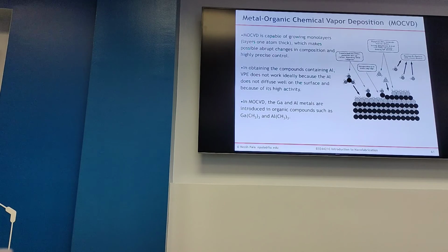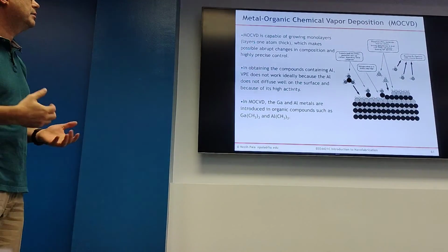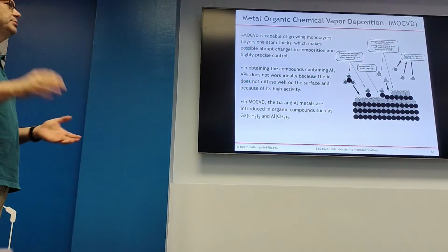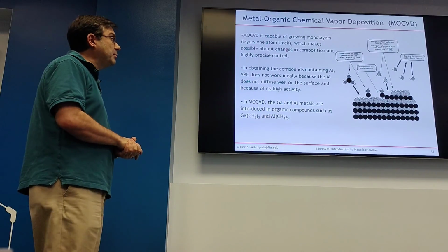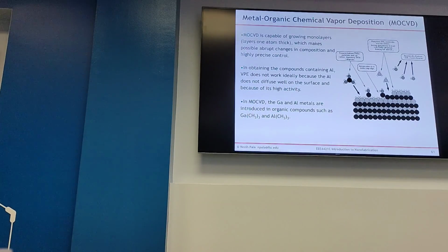You can dope this second layer whatever you want to dope. Okay, that's the advantage of silicon CVD. MOCVD, this is again very, very common, widely used method for gallium nitride technology nowadays. All your LED lights are produced, or the material for LED lights, blue lasers, etc., are produced using MOCVD. So this is metal organic chemical vapor deposition.